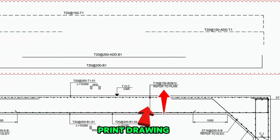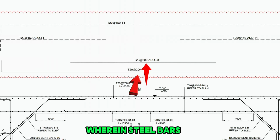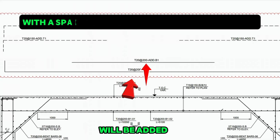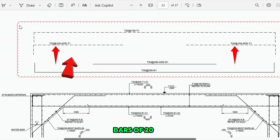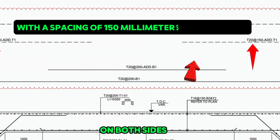In this blueprint drawing, we check the design of additional bars in the slab, wherein steel bars of 20 millimeters with a spacing of 200 millimeters will be added with additional B1 reinforcement. The top reinforcement will have steel bars of 20 millimeters with a spacing of 150 millimeters on both sides, along with additional bars.